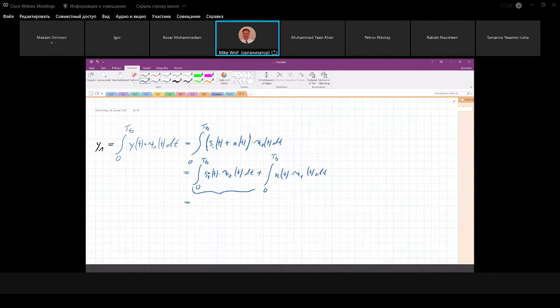So basically, if we had a multi-dimensional signal space, we would obtain the signal vector with this equation. But now we only have one component, so we only get this single component signal vector. But this fully describes our signal. So we know this s_i1 is alpha plus or minus square root of E. And then we get, let's say, the projection of the noise in our signal space.